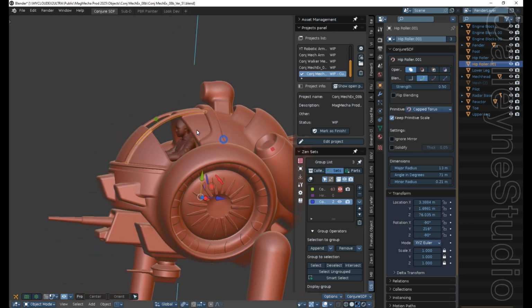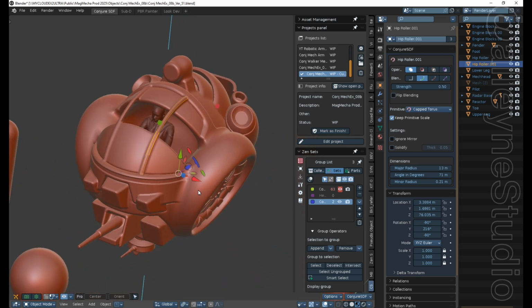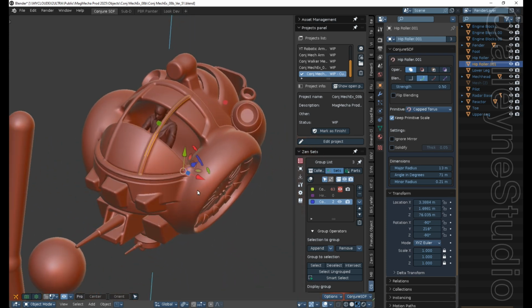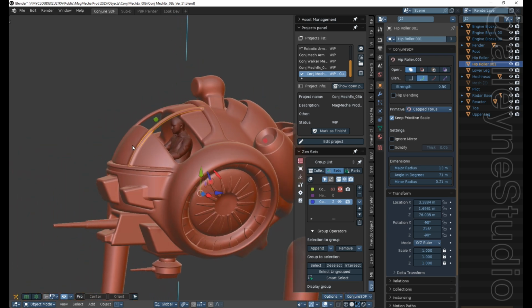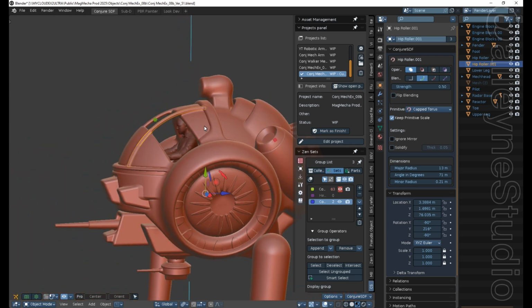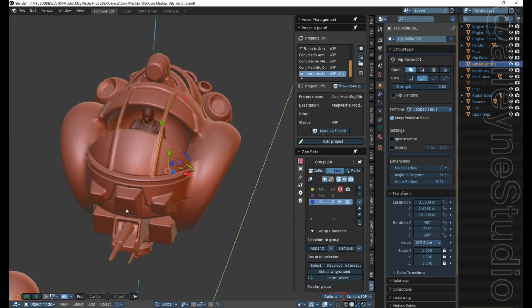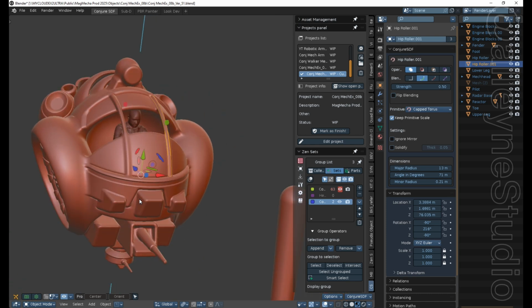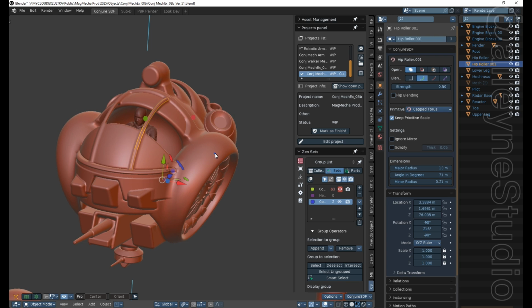Now it's open up here, but I thought having some sort of bar system, some sort of restraining system that reinforces the integrity here in case this thing was to fall and roll, protecting the pilot. Not just these two little bars, but a system. Eventually I'm going to close up this area, so it's probably going to be like a roll cage scenario.